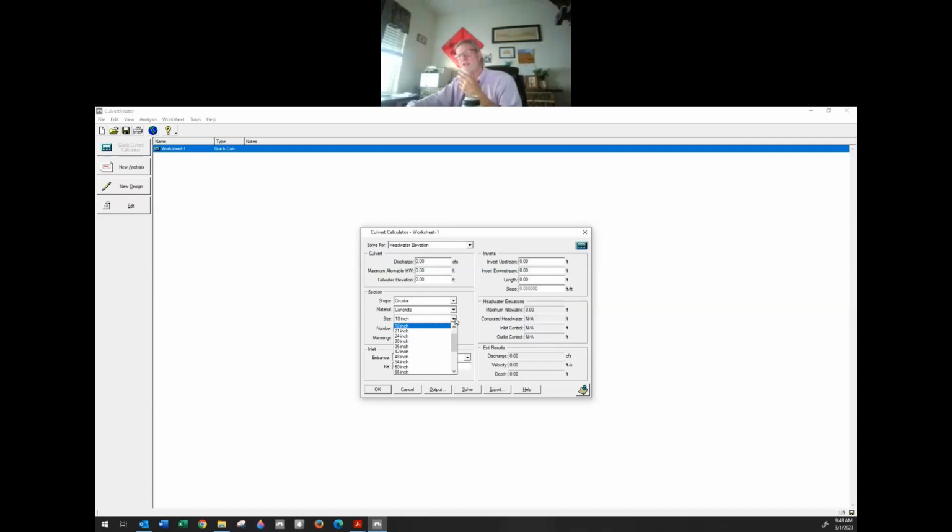For the calculations that you guys are doing, if you have an 18-inch pipe and it's being resized down with CIPP, you could go ahead and assume that's an inch and a half thick or so. And I saw 15-inch was one of the options, so you could probably use that one, and that would be okay for you guys, and avoid trying to do a custom size.